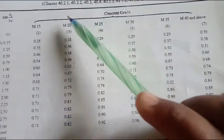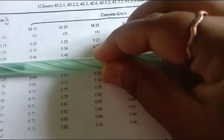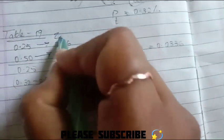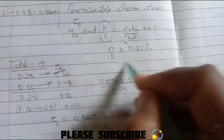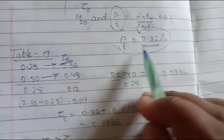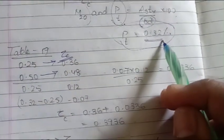So we are designing it for M20. So check this. 0.25, 0.5. It is 0.36 and 0.48. Take the value and note it down. For 0.25 and 0.5, whatever the tau c value is there, this is the tau c value. For the pt value, this is the pt value, 0.32. So if for 0.5 this is the value, and for 0.25 it is this, we have to now find out what is the value of tau c for 0.32.